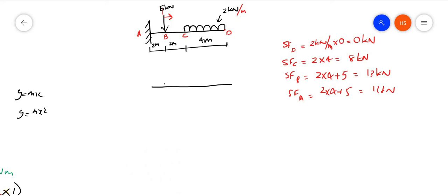So I am drawing the shear force diagram. The baseline is drawn, and everything is positive only. Therefore here it is 0. Marking here, then here it is 8 kilonewton, then there is 13, and then 13. So how can I join this? This will be a linear straight line. From here it will be a constant, again a constant, like this.